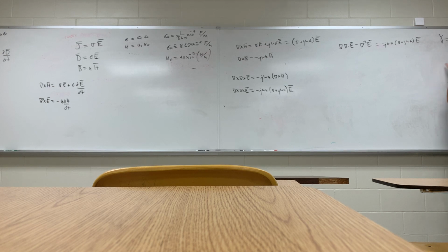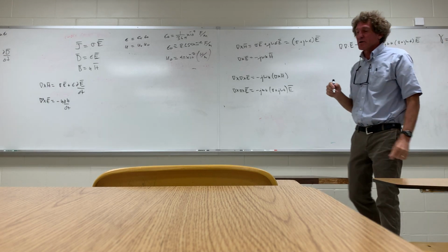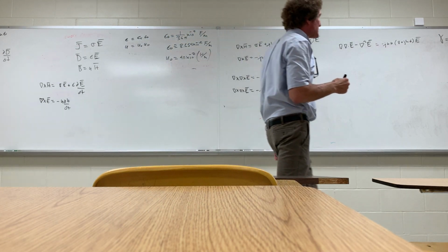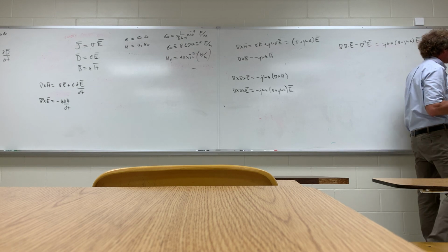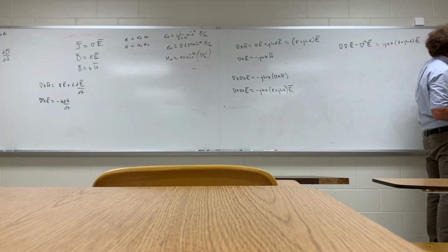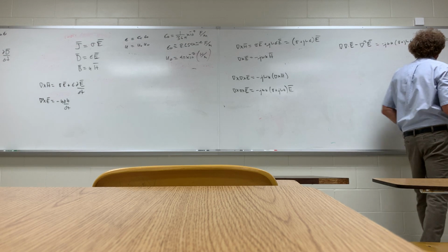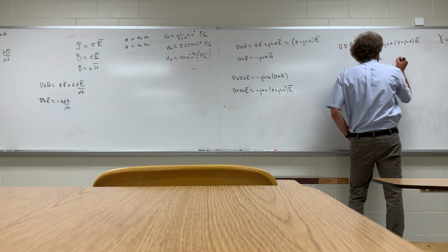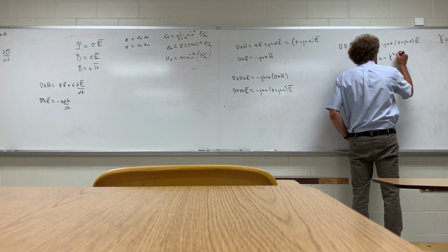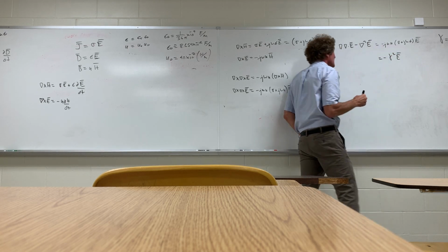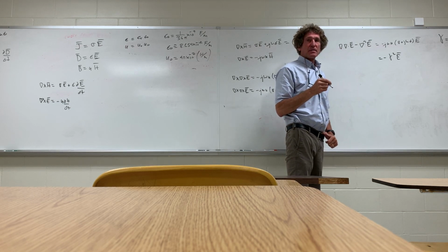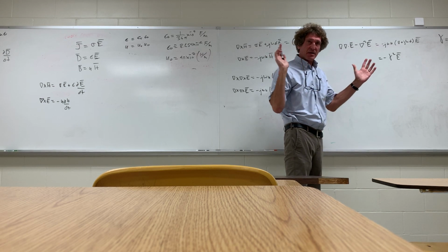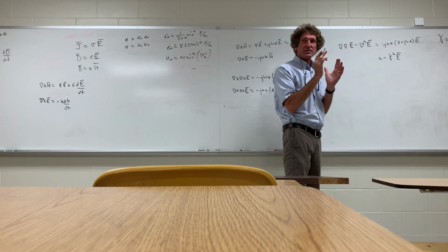So remember, this is called gamma. It's the propagation constant, and it's equal to alpha plus j beta. You'll see why it's important to break it out like that. We're giving it as the square root of j omega mu times sigma plus j omega epsilon. Now that's what's in front here. So now I can rewrite that side of the equation simply as minus gamma squared E. Y'all follow me what I've done? The only thing I'm doing is creating a constant that takes care of all those terms, so I can just work with that constant.